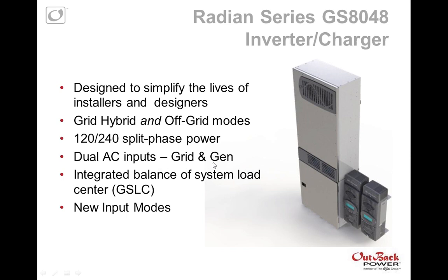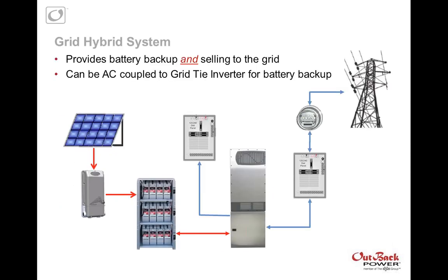There's also dual AC inputs. We call them grid and gen. They're electrically the same, but this eliminates the need for an external transfer switch. And then we have some of these new input modes. The grid hybrid system provides battery backup and selling to the grid.